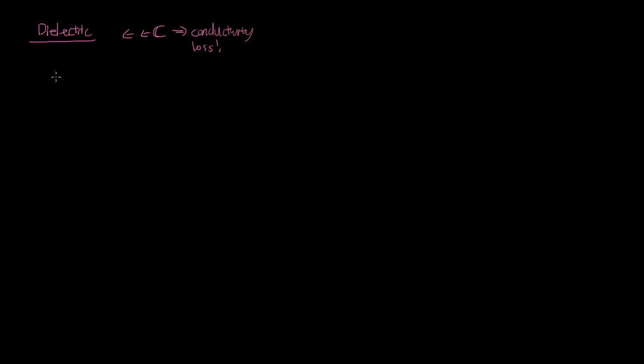Let's start with our definition of the wave number. Remember that with our phasor form, we have our propagation number k, which is in units of radians per meter. In our phasor form, for a wave propagating in the positive direction, we have e to the minus jkz, where k tells you the amount of phase that changes per unit meter in the z direction, right? So now let's define this jk as a complex number. Let's say jk is equal to alpha plus j beta.